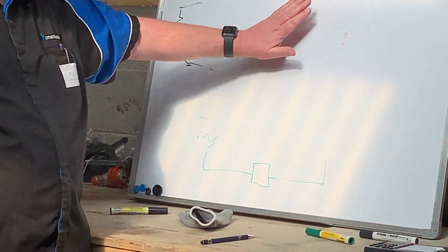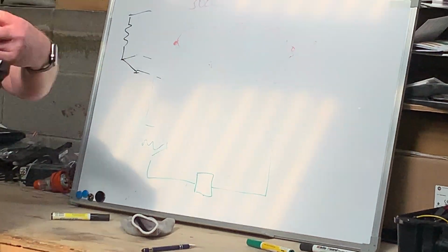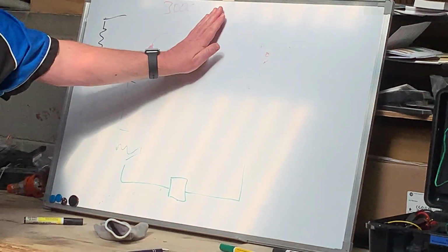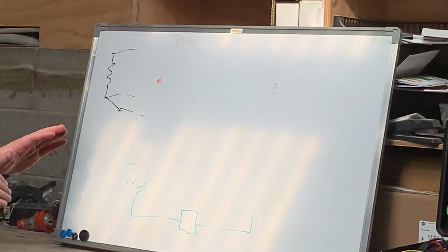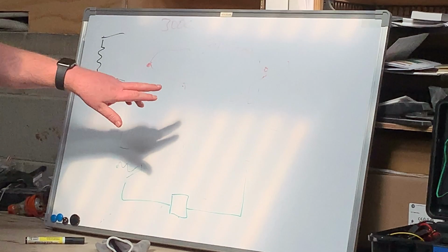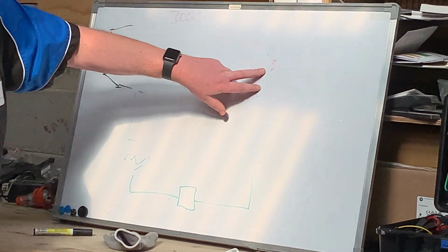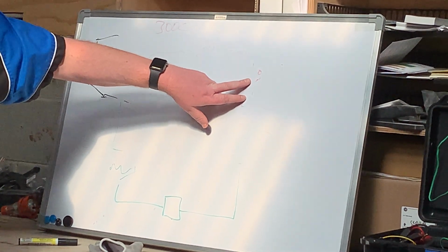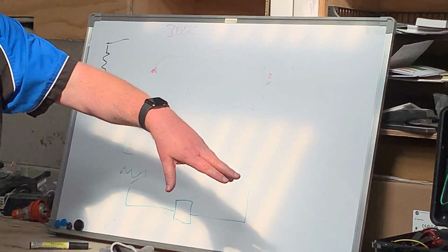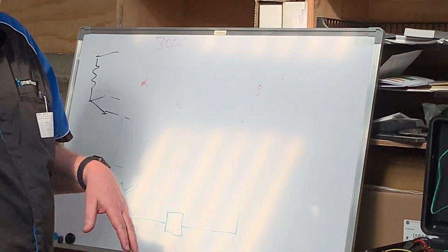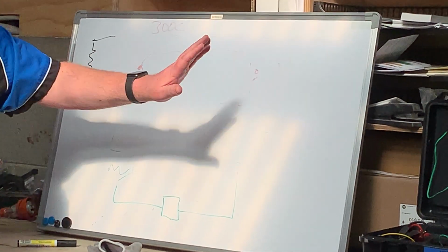When we teach people and say a thermocouple works by two dissimilar metals producing a millivolt signal, it's not quite true. They're lying to you. It's simplicity. What in fact happens is that instead of a bucket of ice, you have a cold junction compensation done electronically. Don't worry about it.